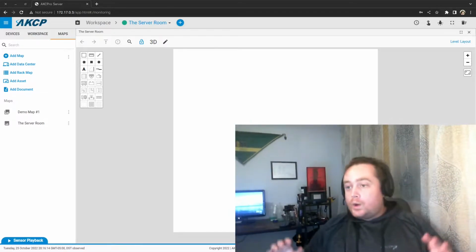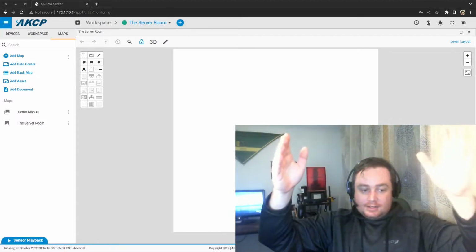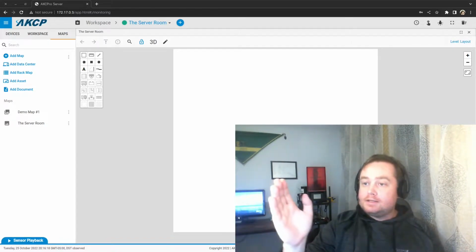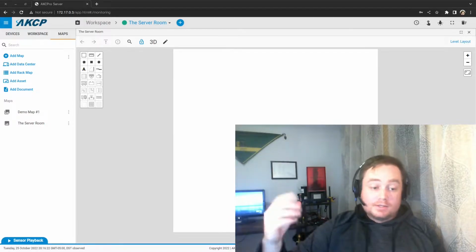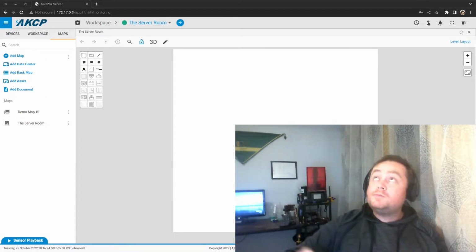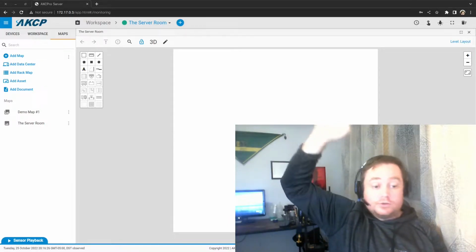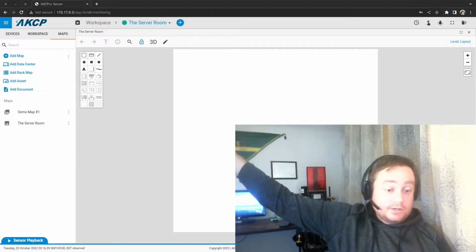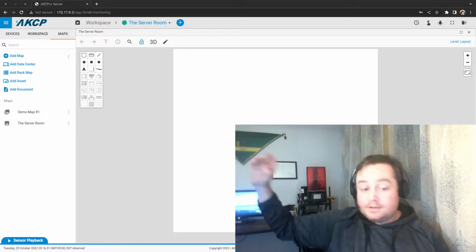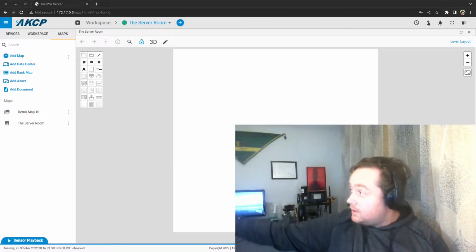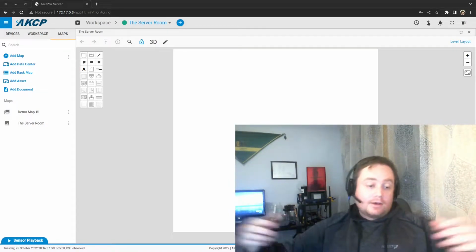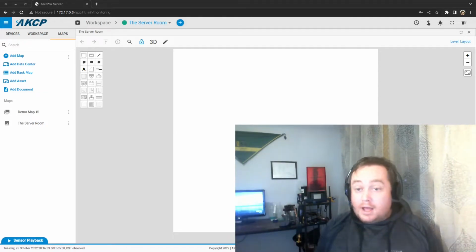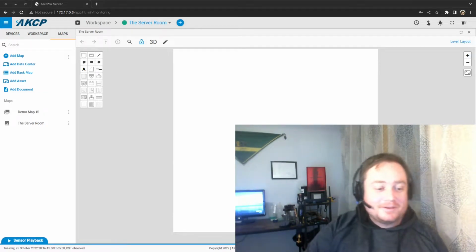So we will put the racks in a row and put the back in a containment that will contain the heat, the hot air, and we will send it in the ceiling to go to the air conditioning unit. Then the air conditioning unit will exit cold air, and the server will take the cold air from the global room. You will see a bit more when we draw it.